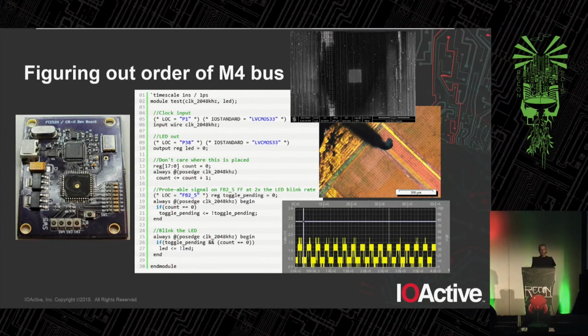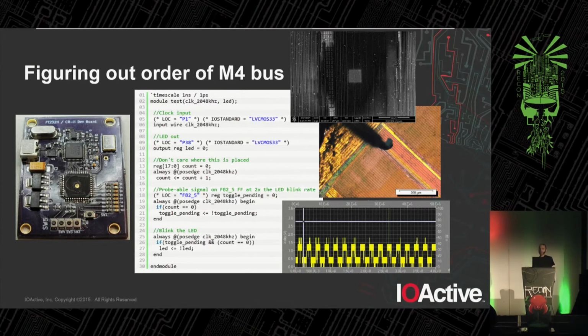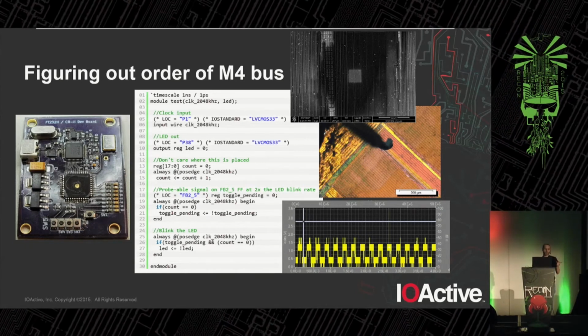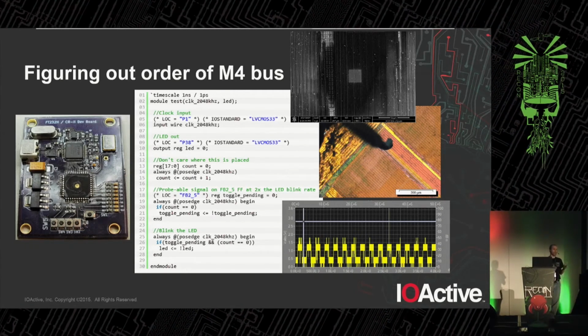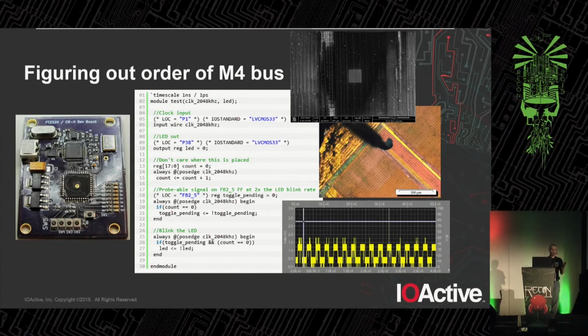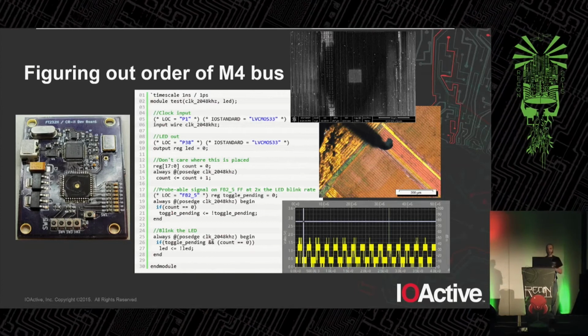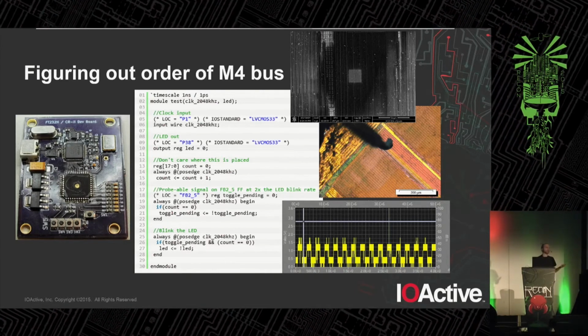So, time to get dirty again. There were a couple of options I considered, but it turned out that one of the simplest was to make a few educated guesses about how things were structured. So, for example, all of the macrocells in function block 1, their flip-flops are probably in a contiguous order in the bus. We don't know where in the bus they are, but they're probably contiguous. All of the input pins for function block 2 are probably contiguous as well. So let's tinker around a little bit.